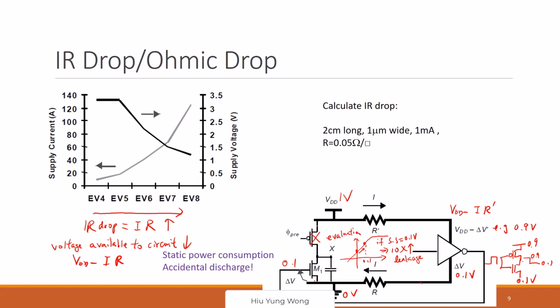Okay, but here I would like to tell you something called sheet resistance. I don't know if all of you know about it. This is about the resistance of a layer. It's talking about ohm per square. So what does it mean? If I have a resistor like this, a square, this is W, this is L, right? You're looking from the top. This is a top view. It's just like when you're doing your layout. I say this equals R square.